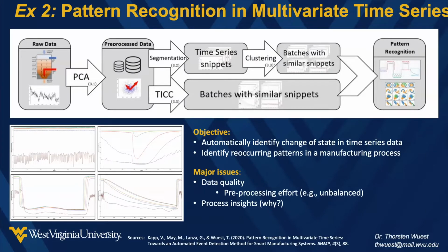So on the left bottom side, you see some of the clusters we were able to identify, but we don't know what they mean in the context, because we only know, okay, this means the heat of the dryer hopper might drop in a certain fashion. But that can have a multitude of reasons. It can be intentional. You can just shut down the machine on the weekend. It could mean there's a leak. It could mean you have a supply problem. Without context, it's very hard to model and to cluster these events.